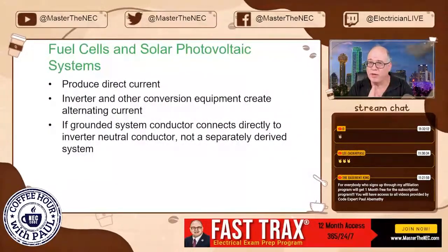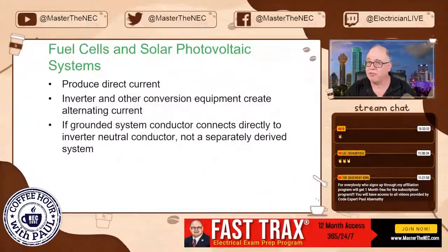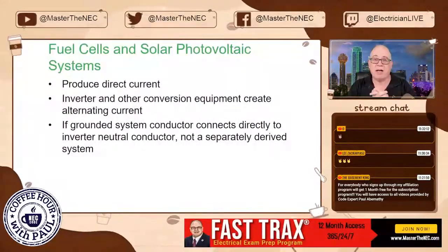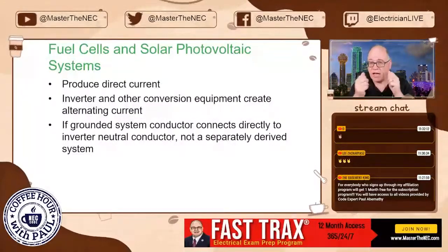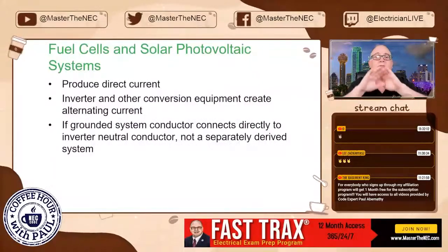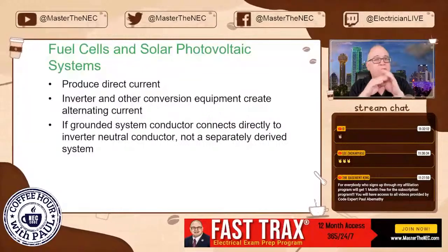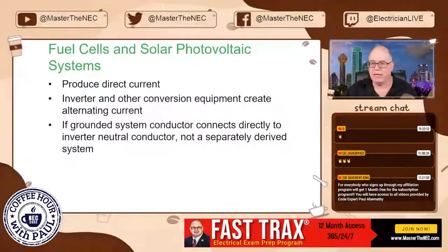And it's so important when you're establishing things to learn whether or not it's separately derived. Okay, so look at those connections. And I'm going to be honest with you, a good ohm meter can do that. A good continuity tester can determine whether there's that connection, but do it before anything's connected, okay? And you guys in the PV world, you're already familiar with this. You probably do this stuff all the time.